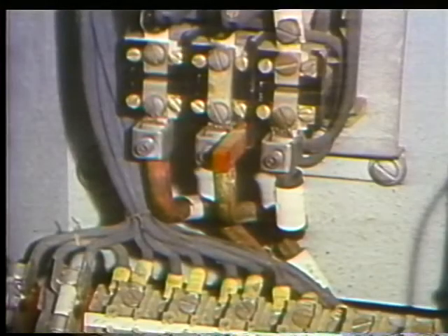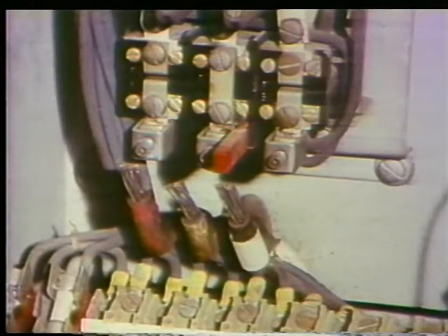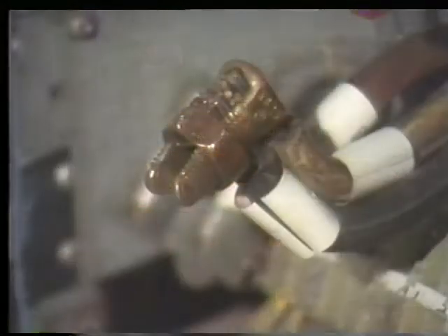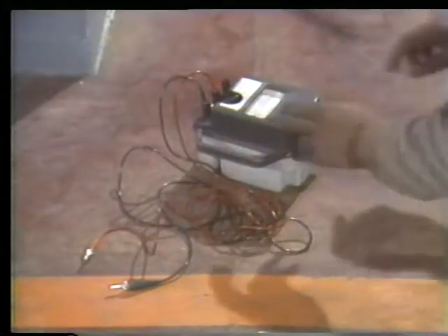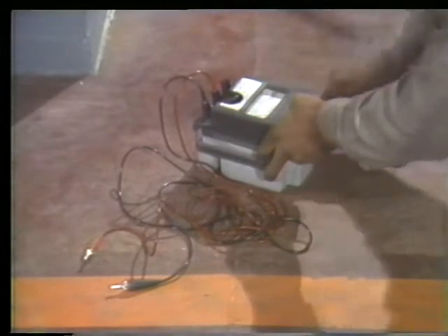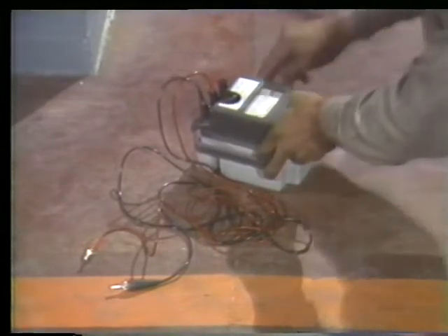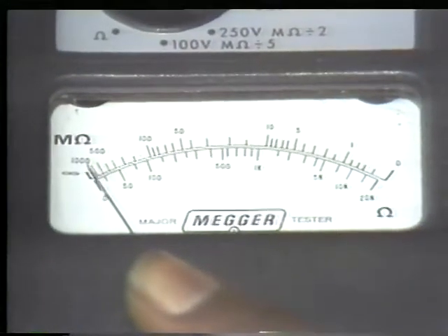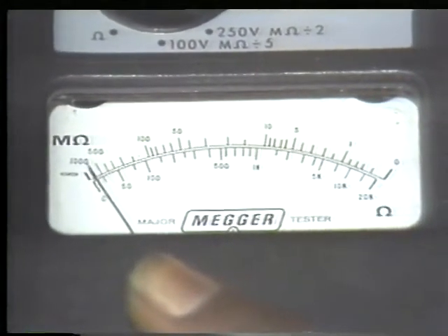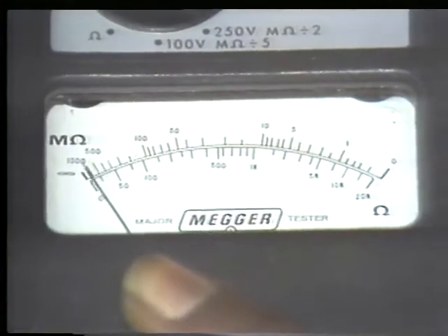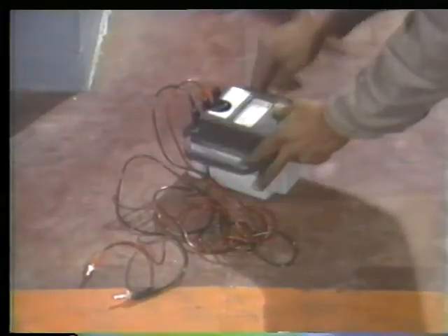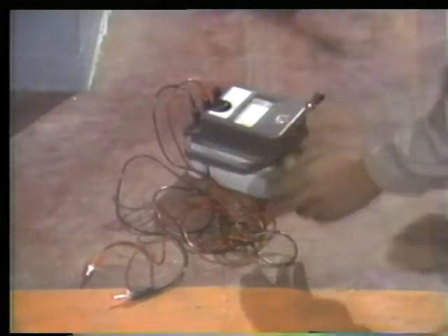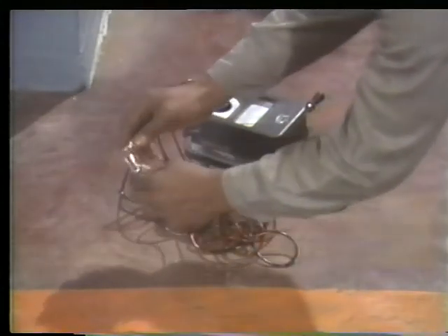In this case, we've disconnected these 3 leads in the motor starter. This isolates it from its power source. Then, the motor leads are clipped together. Before going any further with the test connections, the megohm meter and its ground connection should be tested. The megohm meter is tested first by operating it to see if it will indicate infinite resistance. Then the leads are connected together to see if the meter will indicate 0 resistance.